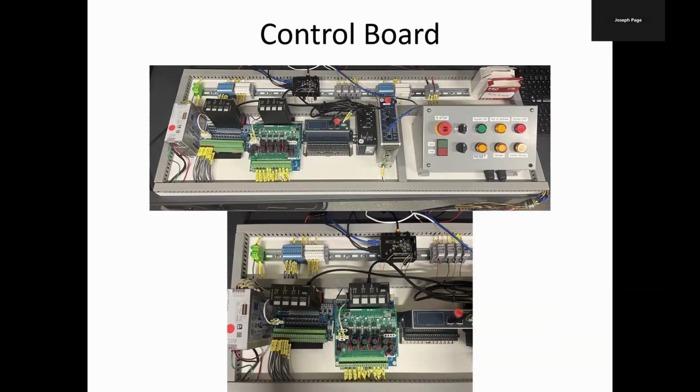And once again, this is the control board. As was mentioned before, all the wiring is done to standard industrial code. A solid blue wire is a 24 volt positive. The white with blue stripe wire is the 24 volt 0 volt. Gray is signal. Red is 120 in. Green with yellow stripe is ground.